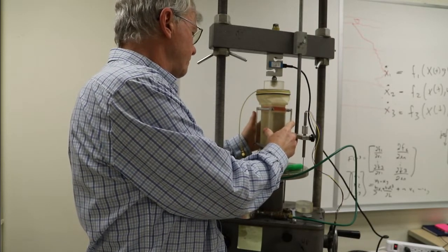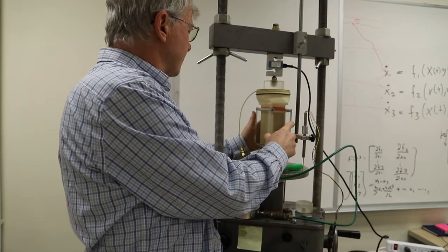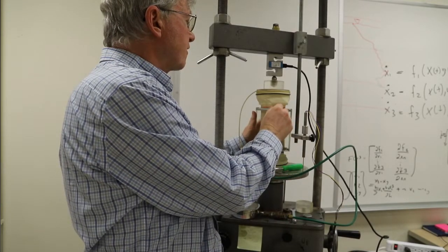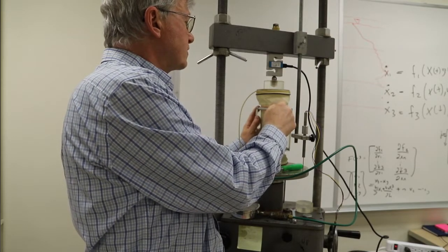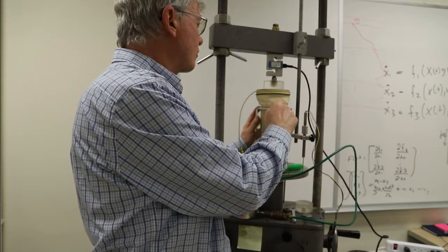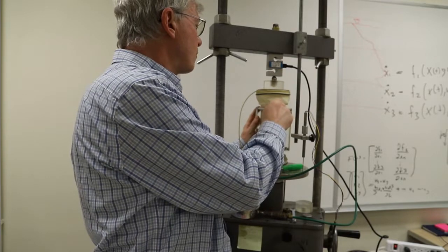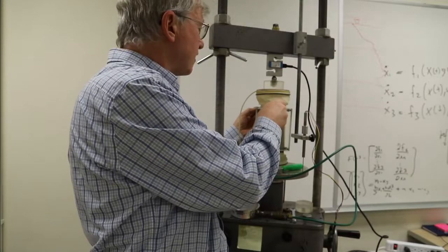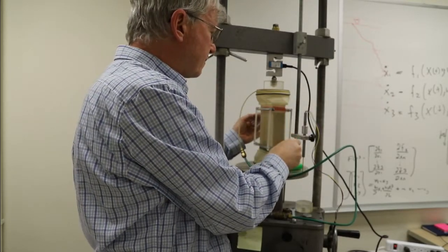So basically we're clamping the specimen in this horizontal direction so that it can't expand toward the camera or away from the camera toward the whiteboard behind the system here. It can still bulge horizontally, but it has to bulge either to the left or to the right.